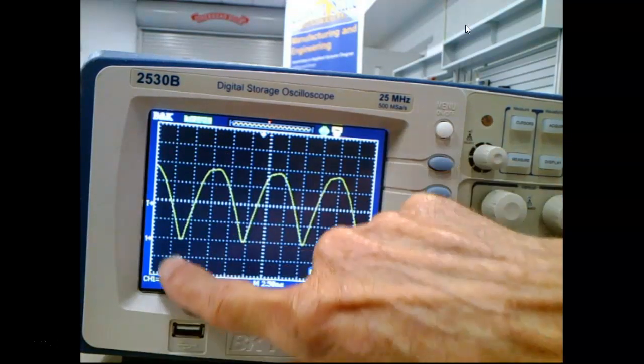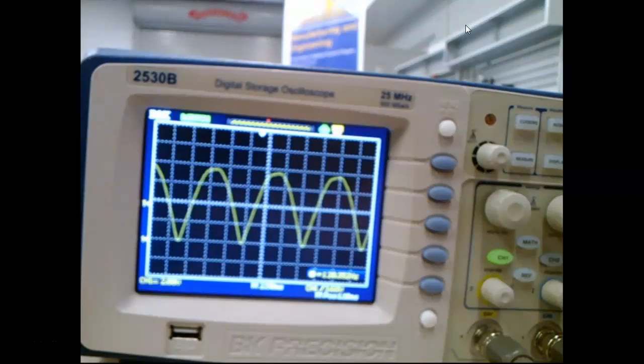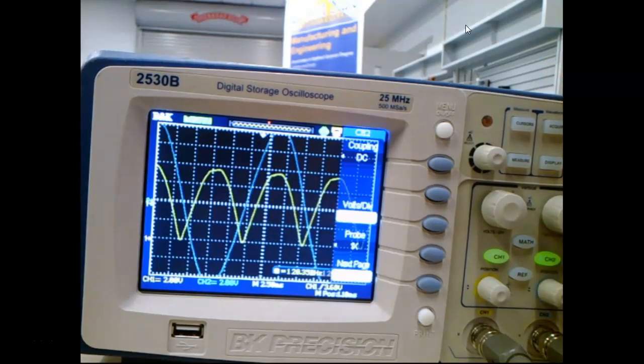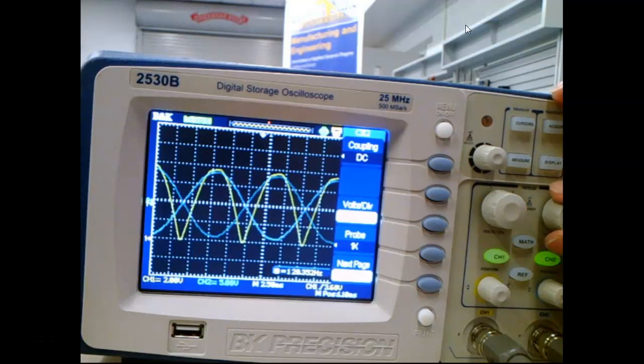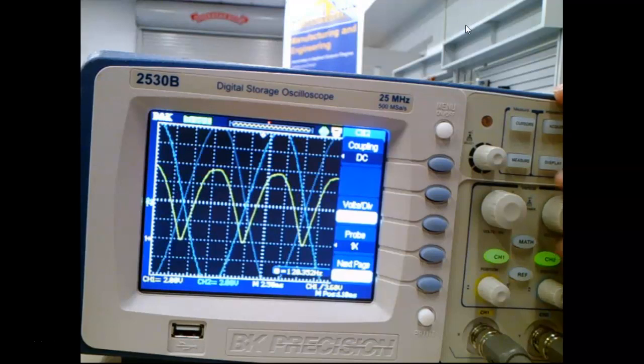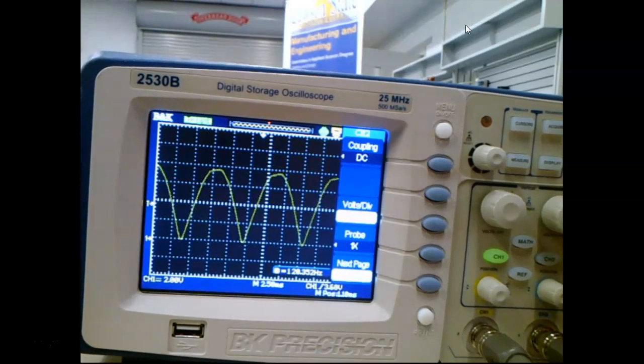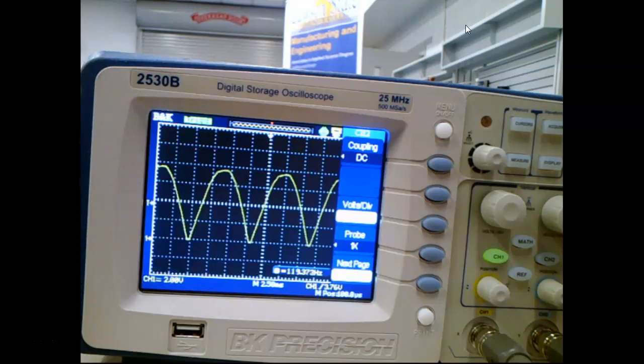Now this is a cycle. So what I've done is I've literally taken the AC and flipped the negative alternation up to the top, right? You understand that? So that means the frequency of my pulses is now, instead of being 60 pulses per second, 120 cycles per second.